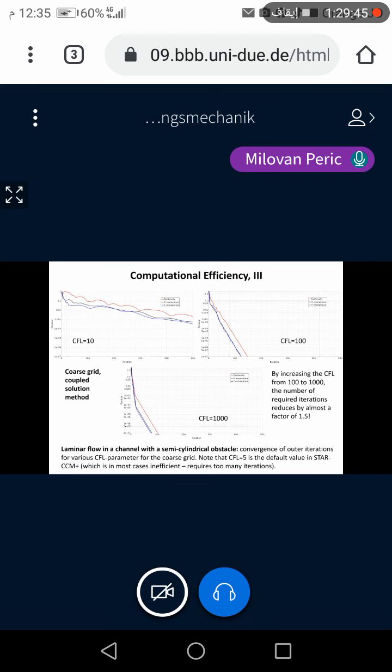Okay, in some codes, in Fluent and in CFX, in Star-CCM+, you also have a coupled solver, which solves for velocities and pressure and temperature as one vector of unknowns. And there you don't have under-relaxation, but you have a CFL number, which is basically, you're doing steady-state analysis, but it's doing marching in a pseudo time, some false time.